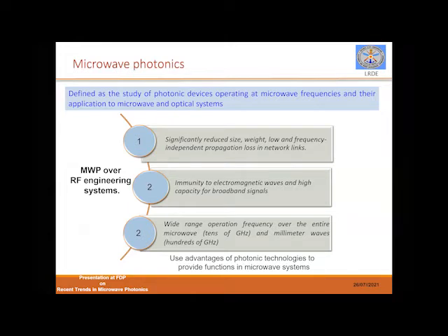Suppose I'm using a component. You will agree with me that because of the high bandwidth capability, previously if I was using a mixer for one application, here, because of the wide bandwidth capability, the same component can be used for mixing signals up to 18 gigahertz or Ka band. Now I'm talking about the RF band, don't get confused. From L band to Ka band, I can use the same component.